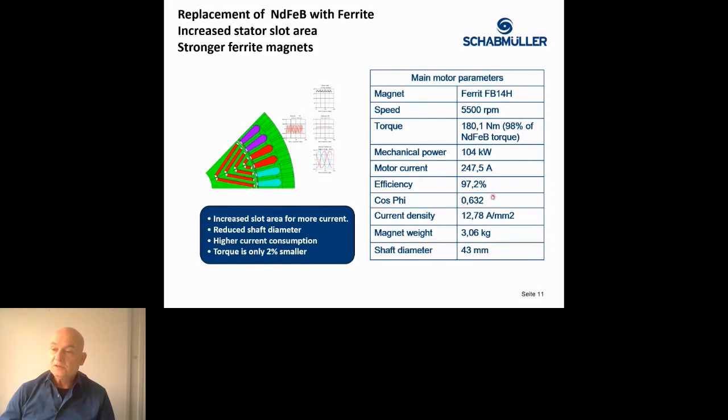This is not really bad, but one needs to keep an eye on it regarding the required inverter current or inverter current limitation, which may be there. And going to a larger inverter with a higher current limit will for sure cost some money as well.